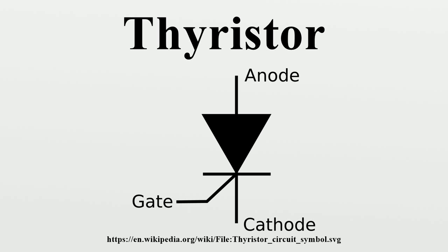Failure modes. Thyristor manufacturers generally specify a region of safe firing defining acceptable levels of voltage and current for a given operating temperature. The boundary of this region is partly determined by the requirement that the maximum permissible gate power, specified for a given trigger pulse duration, is not exceeded, as well as the usual failure modes due to exceeding voltage, current or power ratings.